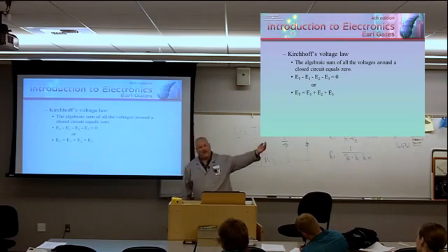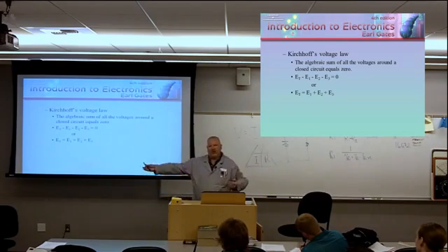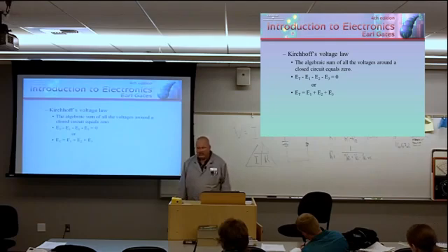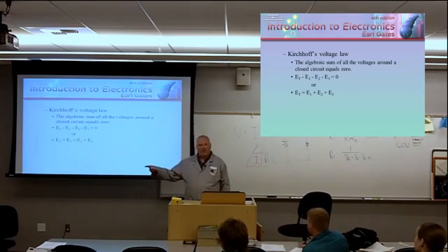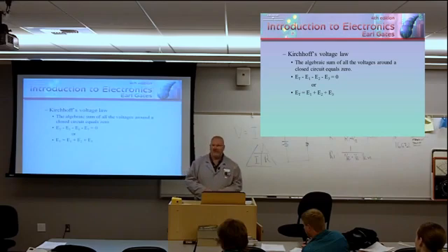If you put 12 volts in, how many volts are going to get used? 12. If you're troubleshooting and you can only account for 11.5 volts, that half a volt is somewhere it doesn't belong. You got 120 volts supposed to be coming out of these outlets. If you plug it in, you only get 98 volts. Something's wrong. If you could go to that box and prove that you got 120 across each leg, but you go to an outlet in your home and you get 98, something's wrong. You find where the missing voltage is, you find the problem.